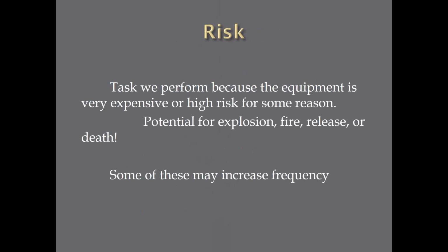Maybe not. In the company I came from, we started off years ago doing them every year. We went to every 6 months. We did thermography and electrical quarterly because there's fines. There's things that can happen over a long time in a year. So is the frequency of thermography yearly good for this facility? Well, no, it wasn't. So we've changed the frequency because they can't afford to have an incident like this again.